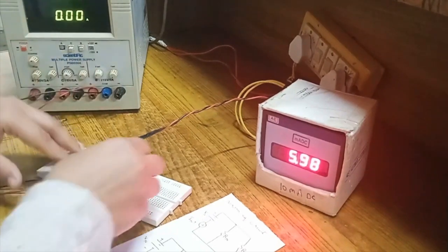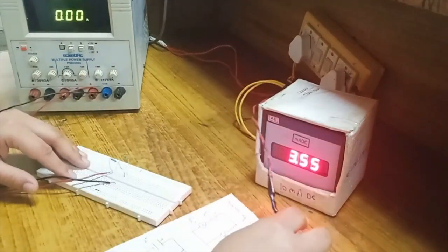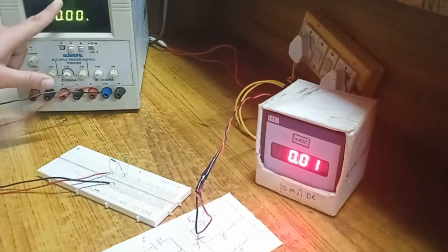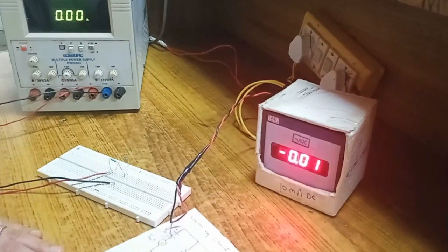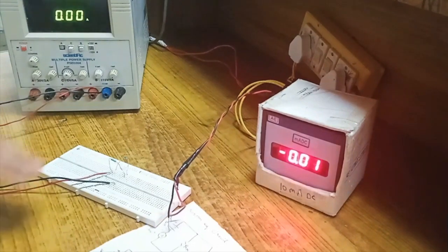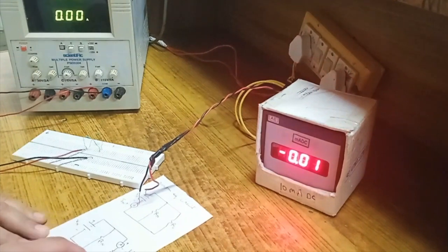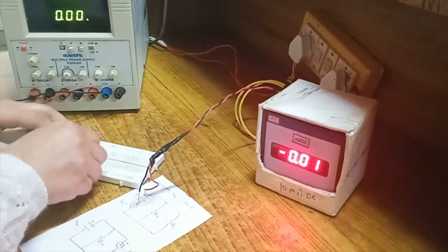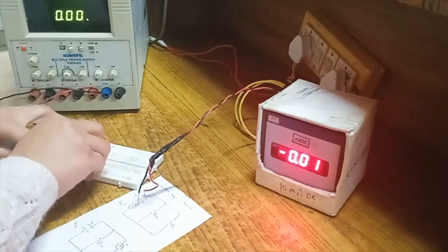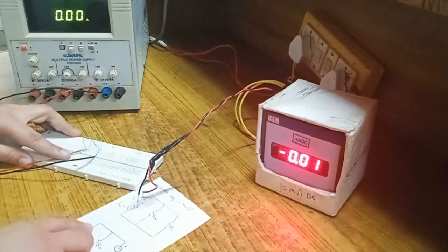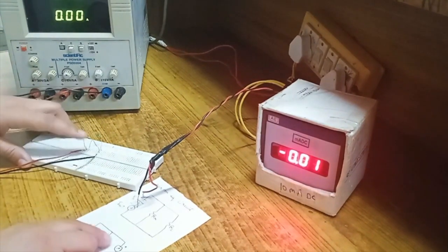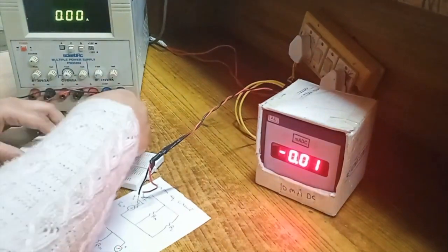Okay. So now the final circuit diagram. Now we have already adjusted Vn. Now we are not supposed to change this voltage. Now let us design the second circuit diagram for the calculation of IL. So the second circuit diagram IL, positive of supply is connected with Rn and positive of ammeter. Negative of supply is connected with Rn, RL both. So first of all, negative of supply is connected with Rn, RL both, whereas positive is connected with Rn and positive of ammeter.